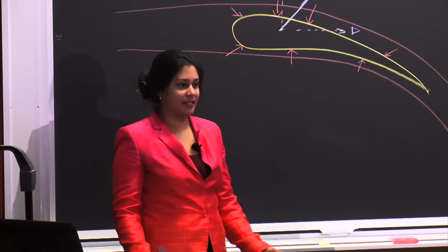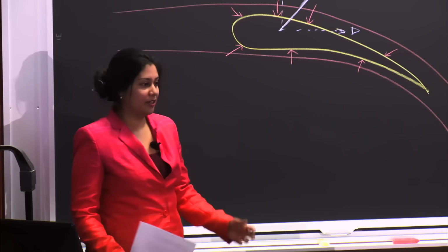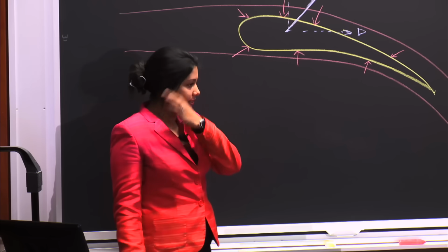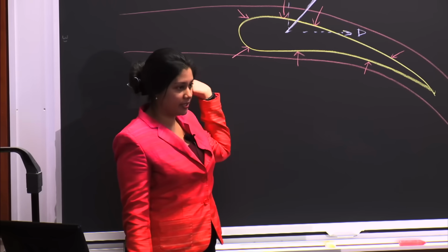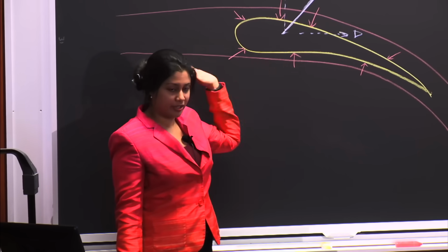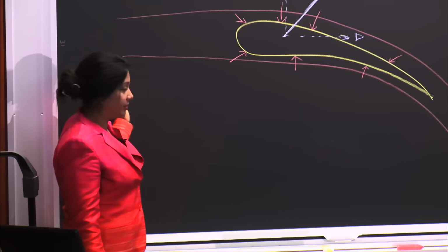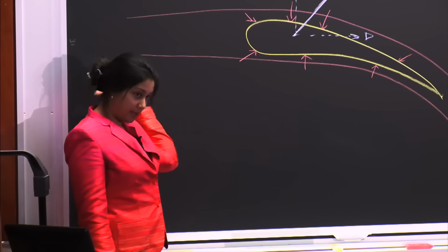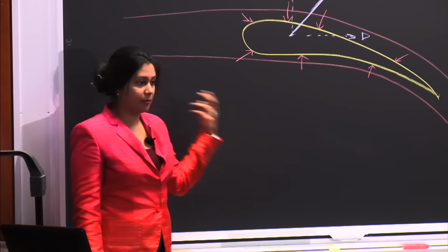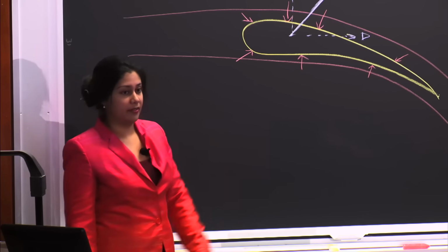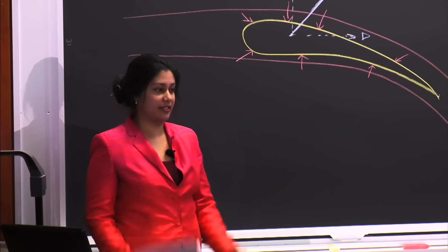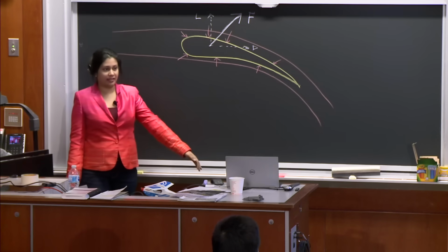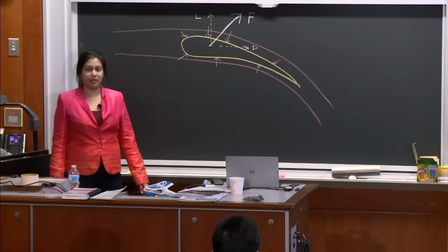Actually, what we're discussing is about frame of reference. So depending on your frame of reference, if your frame of reference is the airfoil, you can take it to be that the airfoil is stationary, and you see the wing to be stationary and the air to be moving past you. If your frame of reference is out here, you might see the air to be stationary and the airplane to be moving through it. So depending on what your frame of reference is, you can actually have the identical result. So the answer is actually that it's the same. Depending on your frame of reference, it's exactly the same, the speed of the air moving past the airfoil versus the airfoil moving through the air.